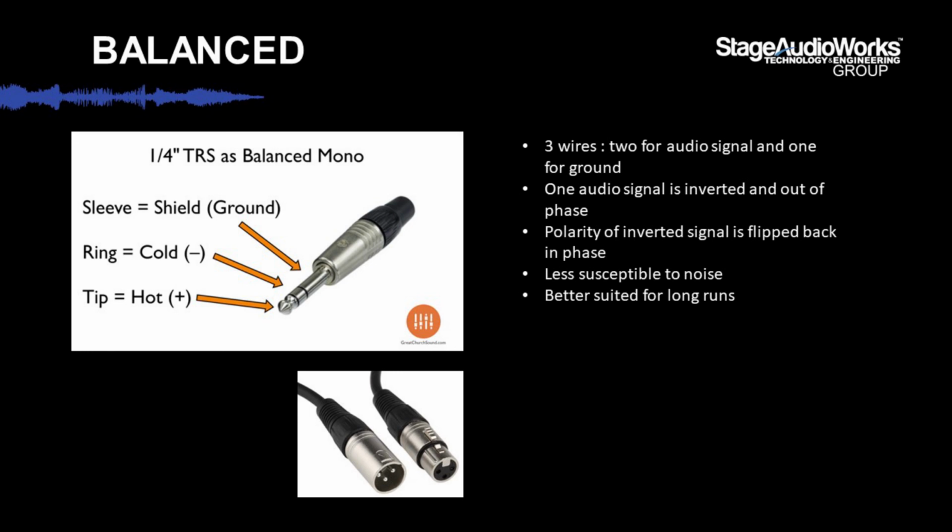Generally speaking, if we make a practical application, if you were making a PC audio cable, 2 rings does not mean it's always stereo. In professional audio, it means it's balanced. But if you were making a PC audio cable to connect your laptop to your desk directly, and the run is short enough that you didn't need a DI box or something, you would generally solder up a so-called fan-out cable, where you would have the mini TRS on the PC audio side and fanning out to 2 TS connectors, one for left and one for right. This way it will work.